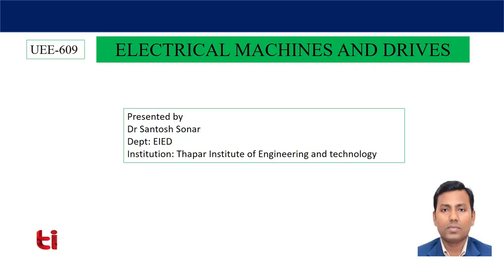Here we will see that to get the desired torque of the motor or the desired speed of the motor, a closed loop system is to be developed. The function of the closed loop system is to process the error between the desired and the actual one through a controller, and ultimately the controller will develop switching pulses which will be fed to the power electronics converter and then to the motor. Let's see those things.